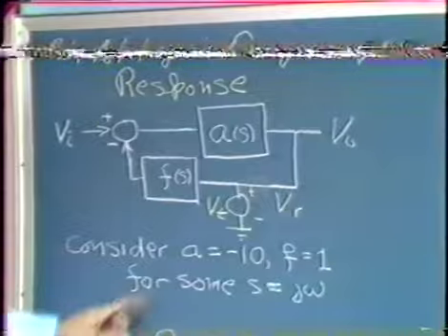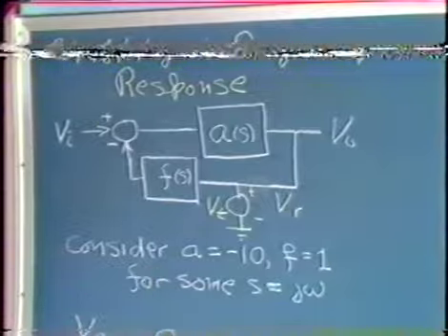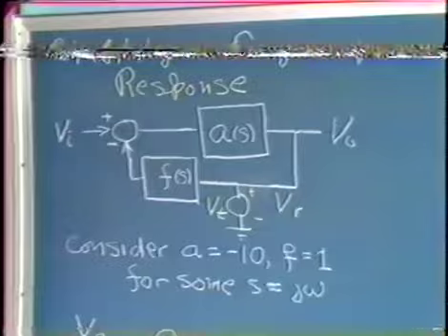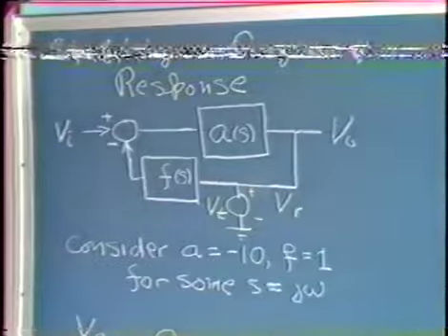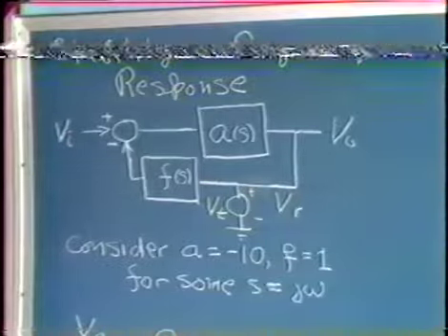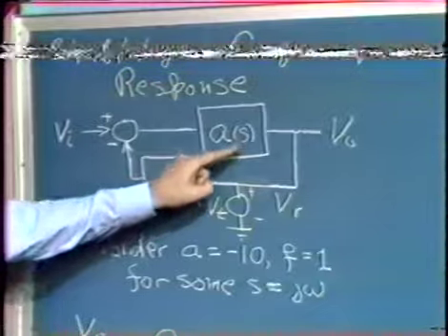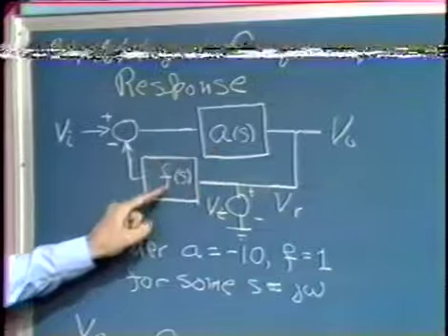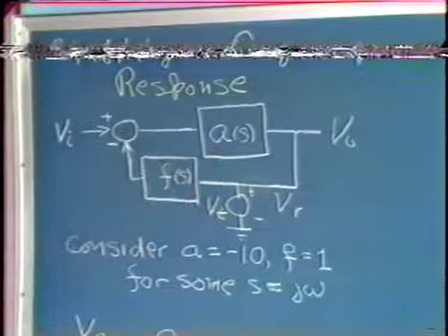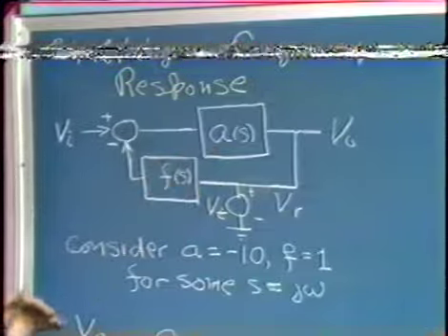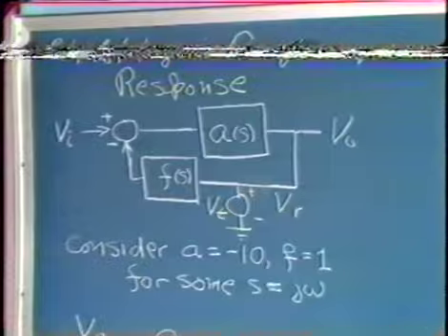In particular, we looked at this situation for a system which had a loop transmission that included 3 coincident poles on the negative real axis, and we found out that for that sort of a system, if we had a low frequency loop transmission magnitude A0, F0 of 8, the system in fact was capable of sustained constant amplitude oscillations.